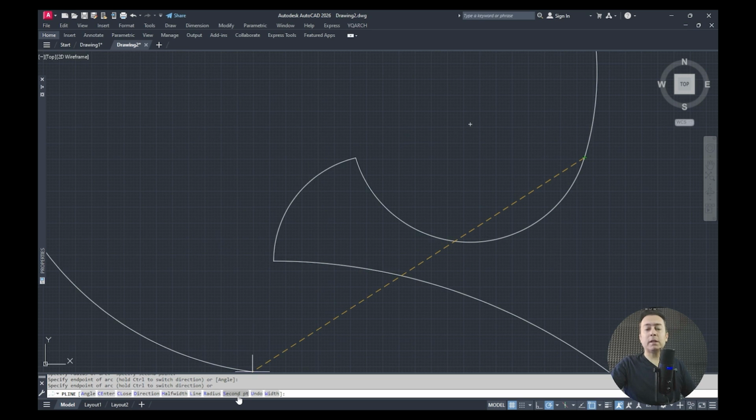Now the second PT subcommand is the same as second point. The second point is based on the mathematical rule that from any 3 points that are not on a straight line, you can draw an arc. Now I have 1 point and another point is the one I'm on right now. If I go into second PT, it asks me for the second point, which is a point on the arc. So I come here and it asks, where is your second point?